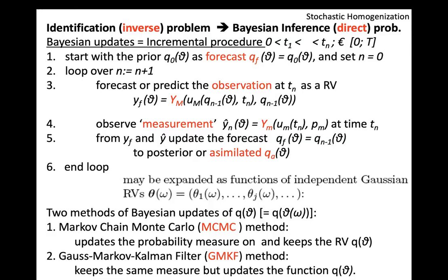But in the inverse problem, you apply your loading and you measure displacement, eventually strain, and you try to understand the parameters of your constitutive behavior, for example, or other types of parameters you might be trying to identify, so that the results you measured fit the behavior predicted by this particular model. This is an ill-posed problem because many different parameters can fit, and you have to do regularization and so on. There are books about inverse problems on how to do it.